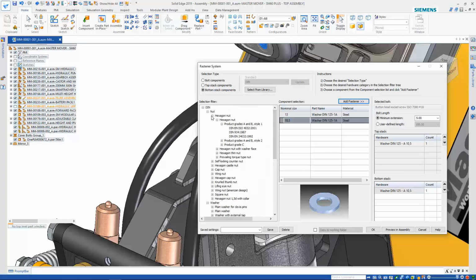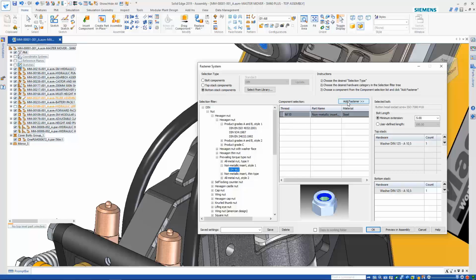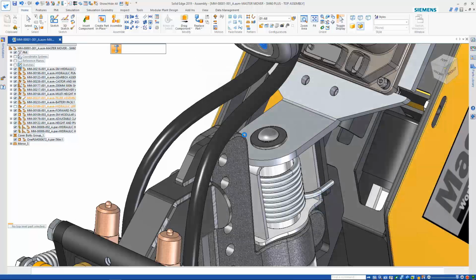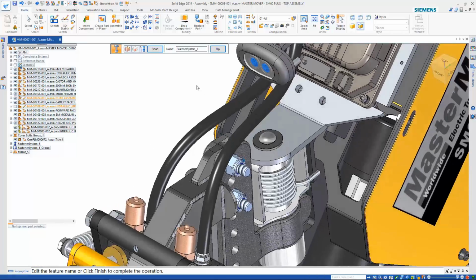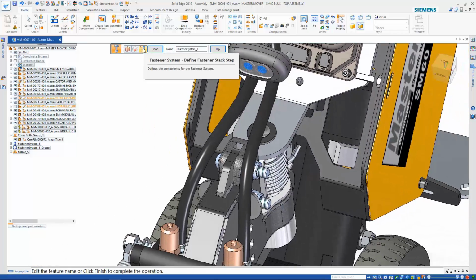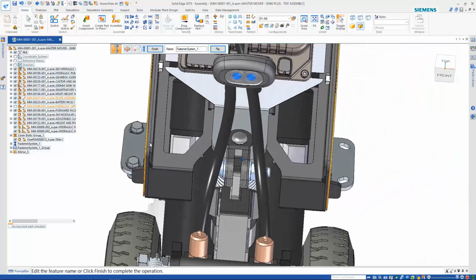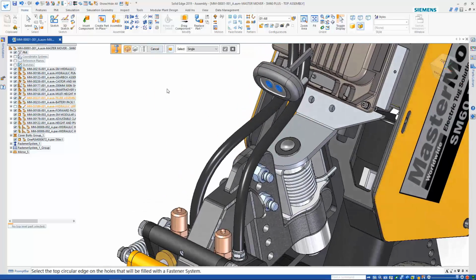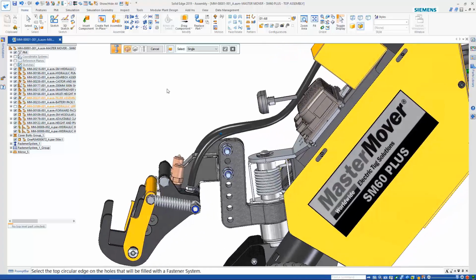And then I'm going to find a nut on there. So I'm going to do a hex nut, American. So I want to use a nylock, non-metallic insert, then 982 M10. It recognises that because we've got an M10 bolt there, and then that fastener on there. And I'm going to click OK. That's then going to generate any bolts that we may not have used. So the washer and the nut probably used before, but it's a new bolt, so that's just going to generate that. So that's looking at a template part and adjusting the sizes, and that's going to pop all those in there for us. So we can go back at any point, back to that step and define, so if I wanted to reduce the depth on those, but I'm actually quite happy with those. So that's bolted in place.